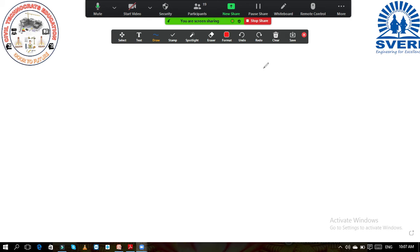In bending we considered only the bending moment about the z axis. We have not considered the moment along the longitudinal axis, that is, along the length of the member. Here we need to consider both of them: the regular bending moment and the twisting moment, or torsion. Combined, we are going to design the sections, and for combining the bending moment and twisting moment we are going to consider an equivalent moment.